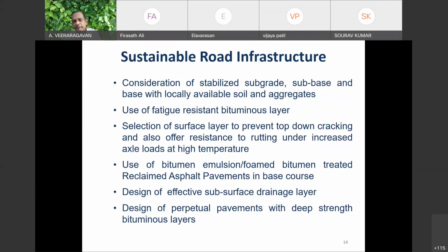So when there's a temperature variation and the pavement is subjected to higher traffic loads, overloading trucks, higher tire pressure, we find the tensile strains develop at the top, with the result the pavement may crack at the top. We always feel that it's only bottom-up cracking that takes place when the pavement bends, but it's a top-down crack that occurs because of climatic factors, overloading, higher tire pressure.